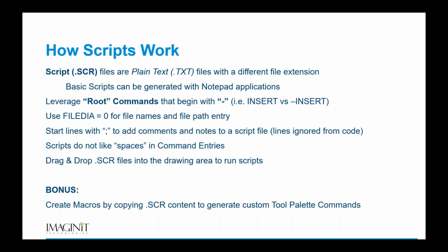So there's a couple of questions that are coming up. Can you use script files to change layer states? You can change layer properties with scripts for sure. You can launch the layer command and then go through any of the prompts to change colors, line types, plot styles, all of those things.